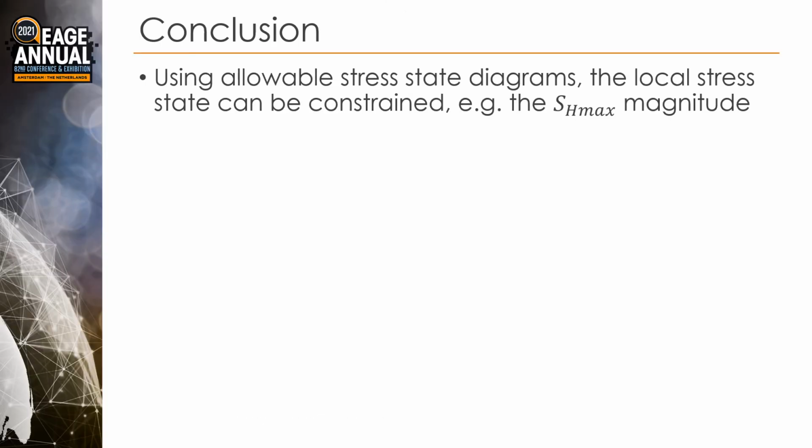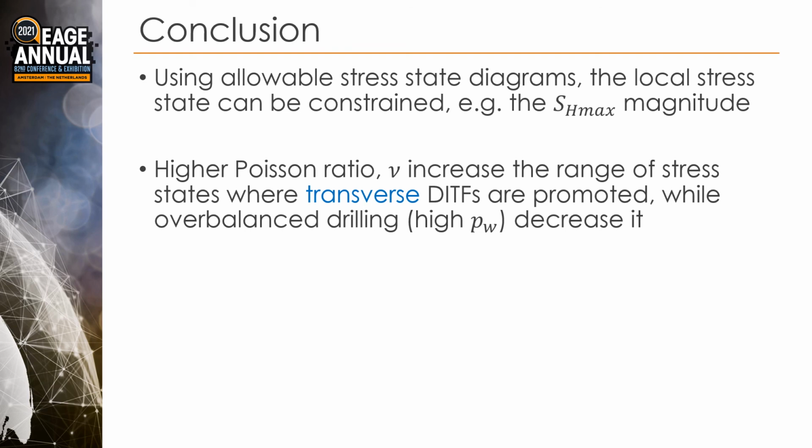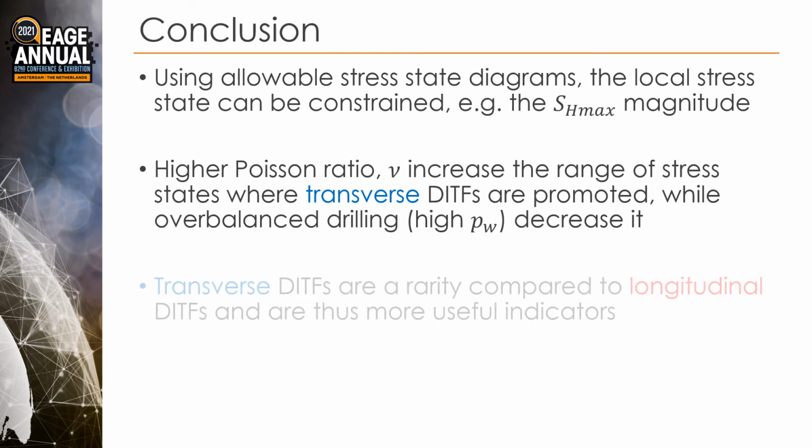In conclusion, we can use allowable stress state diagrams to constrain components of the local in situ stress state, such as SH max. Higher Poisson ratio and low wellbore pressure increase the size of the blue region, which means more promotion for drilling-induced tensile fractures.